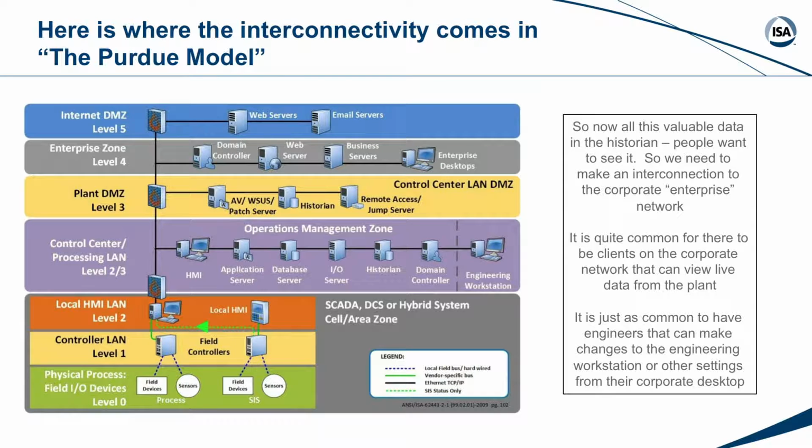And that controller may have, say, several hundred or several thousand control points in it. And then you have dozens of those controllers that are networked together across perhaps a high-speed redundant Ethernet backbone that runs through the plant. And then those controllers get networked once again, or collated once again, to go to the interfaces to the business system side of the house, right, through your demilitarized zones. Typically, that's the way you'll see most things laid out.